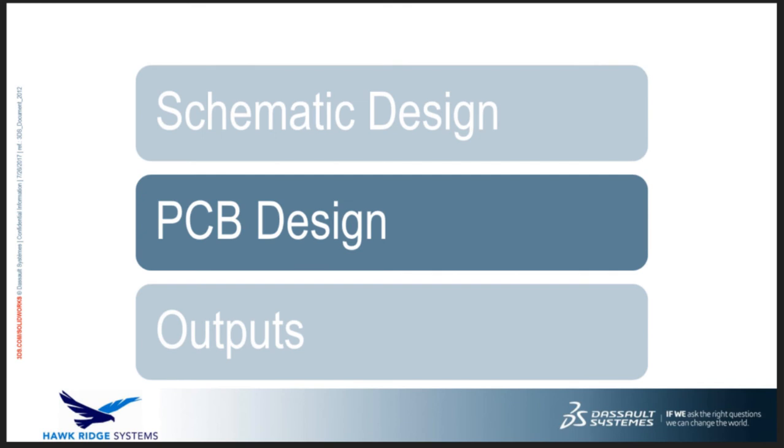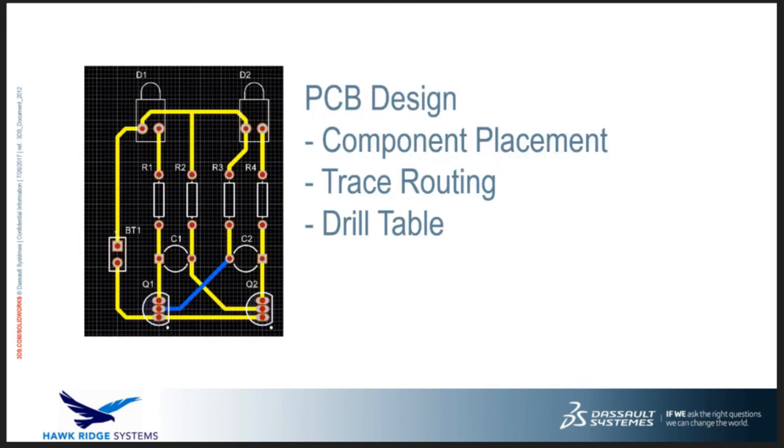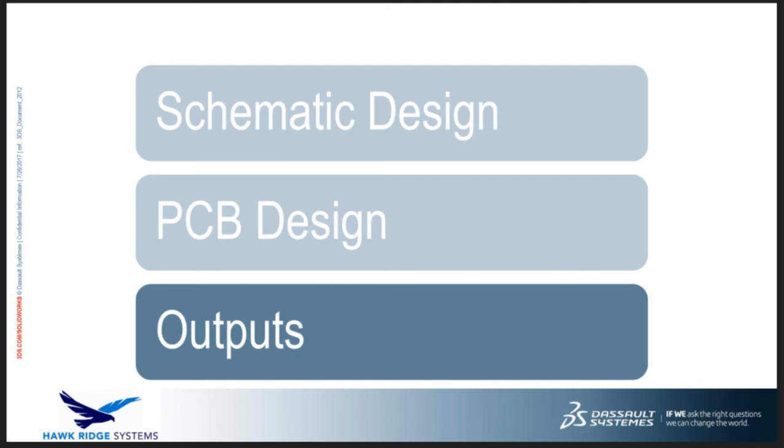So during the circuit board design piece, we saw demonstrated easy component placement as the compilation of the schematic automatically pulls those footprints from the library, placing them on the work surface, automatically doing the electronic connections driven by our schematic. We completed the trace routing, and I'm going to add that drill table, which represents the holes, the quantities, the graphical representations for the drawing. And then we'll move to the outputs.